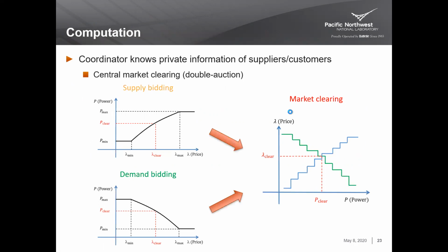So this just shows how the market clearing process works. You'll have bids from the individual TCC agents for certain commodities, and for VAVs, like I mentioned, that's airflow or needed cooling. Those are aggregated up to the AHU level.